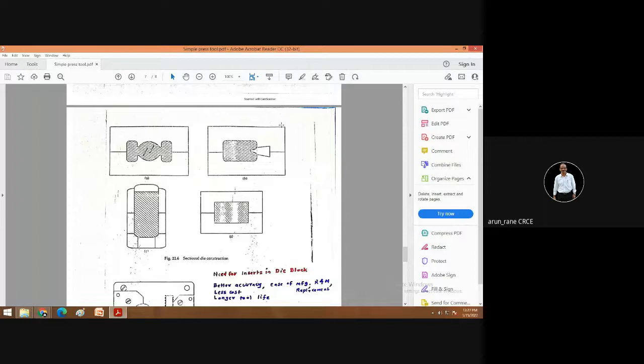Like this now here. So this is one piece, this is another piece, means I want this. और ये एक और एक पीस ऐसा डाल दिया. If you want to manufacture like this, then this is going to be very difficult. Similarly अभी ये देखो. Okay, so if you make it like this, आपका मशीनिंग इजी हो जाएगा. Now this corner you can mill easily with the help of the end mill on a vertical milling machine.